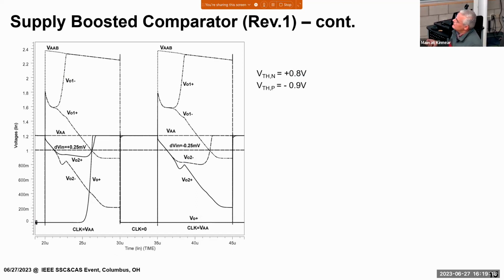Okay. And here, the input is negative. It already makes a decision here while the supply drops about, I don't know, 5% or something. At this point, it's already tripped. It trips early. That's the idea actually. As long as you start making a decision before it drops too much, you don't really care about it. That's the idea of this boosting. And again, this can drop much faster, and still these two are going to go down, and maybe somewhere here they are going to start splitting, even though this drops maybe 20% down from the 2.4.